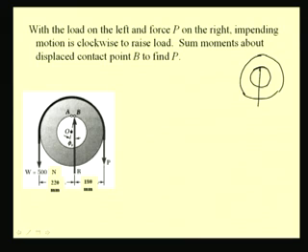Originally the point of contact is at A, and as the pulley tends to move in this direction, for exaggeration let us keep that this is the diameter of the shaft. The point of contact slowly shifts in this direction, and once it reaches some maximum value, it starts to slip and the pulley starts to rotate with respect to the axle.